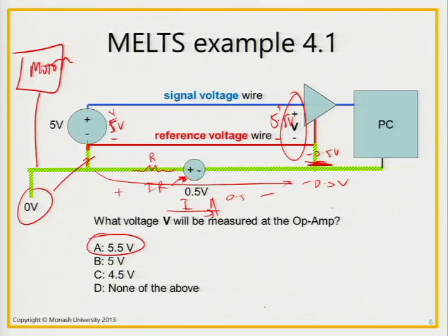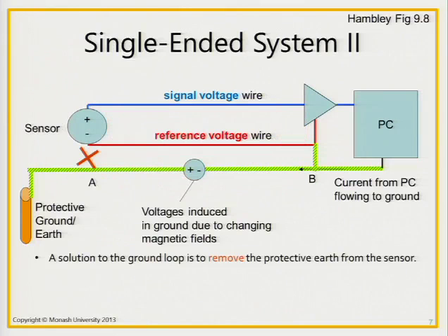Okay, so what are solutions to this? Well, what we could do is disconnect the sensor wire over here. Then the voltage here will be the same as the voltage here, and it will be whatever it is through this earth loop, through this voltage source connected up to here, so you'll have the same voltage all the way.